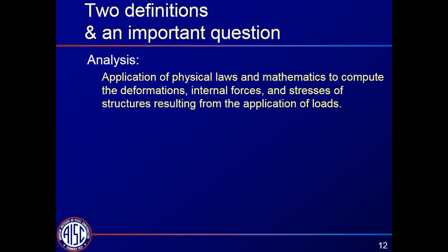So if you do your analysis and apply the forces, you should be getting the right stresses in each of these joints. That's a pretty ambitious definition of analysis, especially when it comes to seismic design, or wind design for that matter, where the exact nature of the forces is not known in advance, and we simplify those forces quite a bit before we apply them.